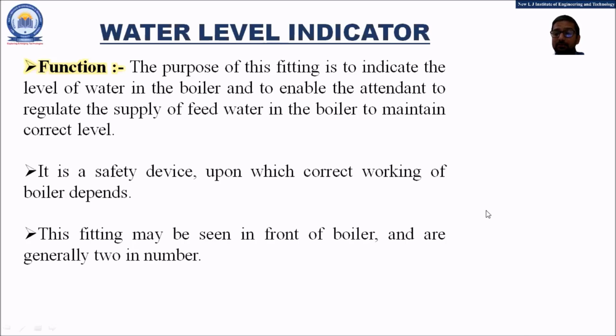If the level of the water reduces suddenly, then there are chances that because of the low level of the water, the temperature can be increased and the pressure can be increased suddenly, and there are chances for an explosion.